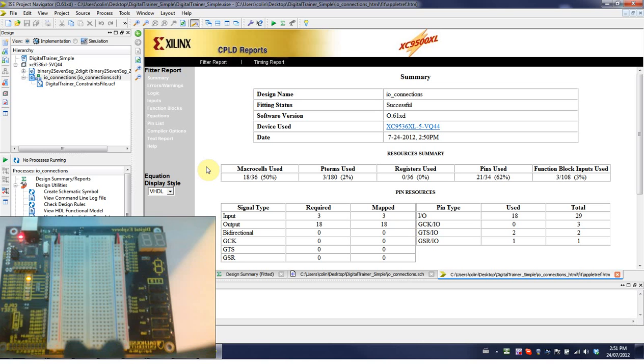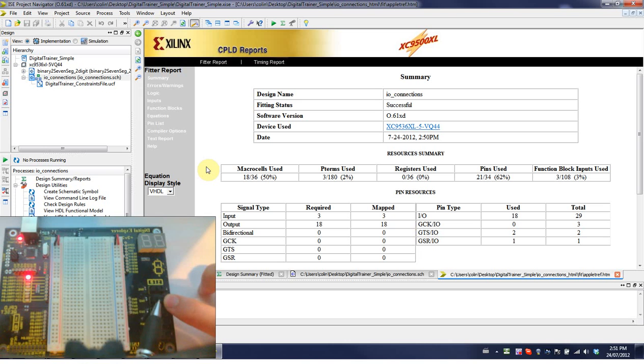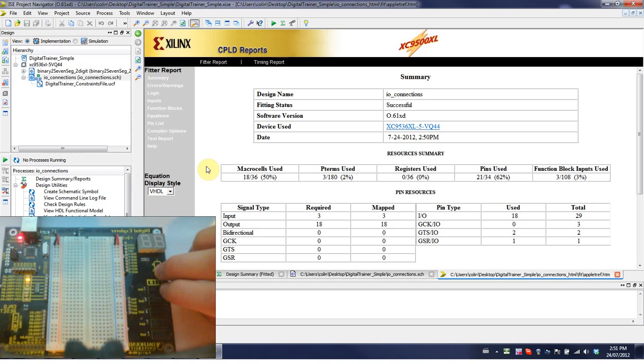So we have 2 outputs here. The first 2 LEDs. And these 2 outputs here are LED 1 and LED 2. So LED 1 is the Q output and LED 2 is Q complement. So we know it's an RS latch, so one of these inputs is reset and one of them is set. So for example, if I click that one, it does nothing. Click that one, it sets the output. And then it latches it, because when I put the switch back to 0, it's keeping the state. So we can clear the output. So again, this is Q complement, and set the output.